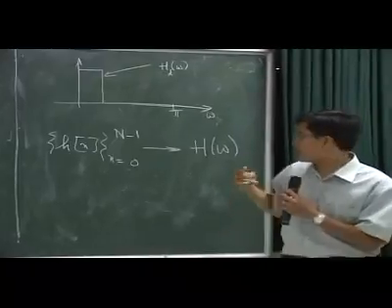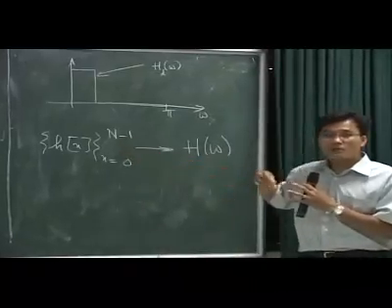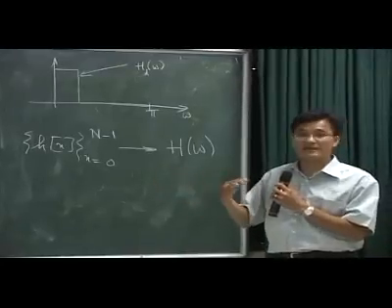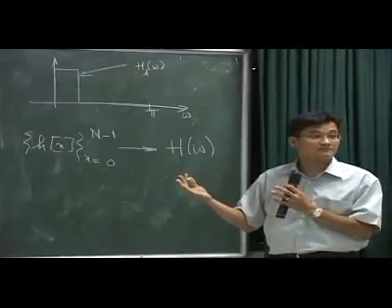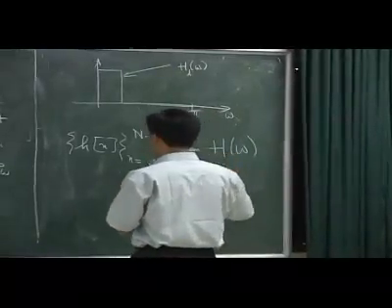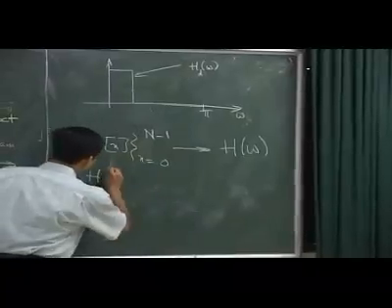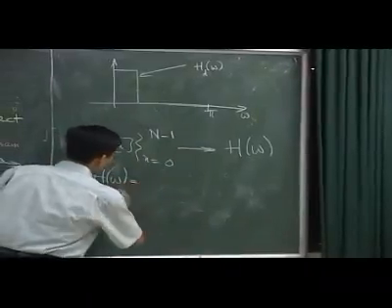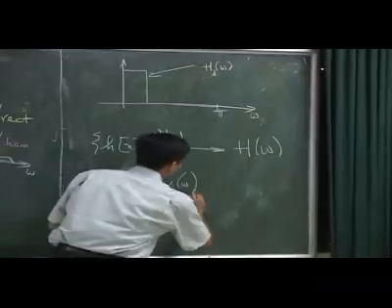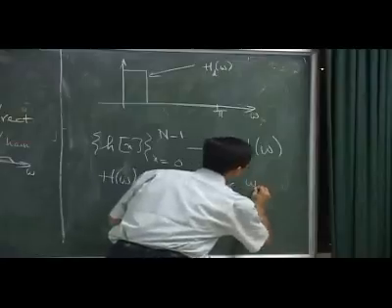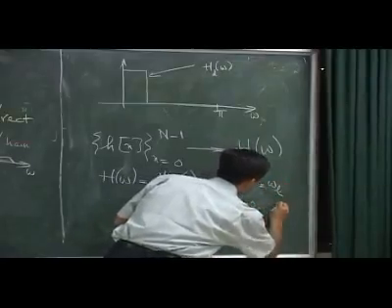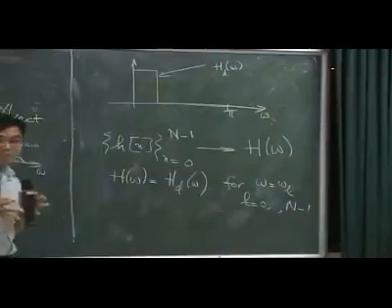So if I have N degrees of freedom here, what is the maximum I can hope for? What is the maximum I can match? N, right? So then maybe now I can specify: I want H of omega equal to H of the designed filter omega, for omega equal to some omega k, k going from 0 to N minus 1. That's the best I can hope for.